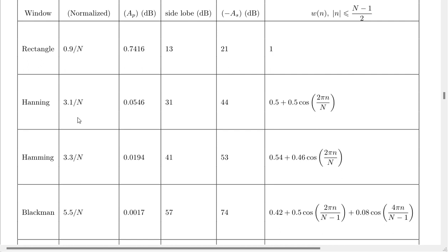Here N will be bigger than what you find for Hanning. And Blackman, of course, will have a lengthy window compared to these two. So, if the mentioned attenuation suffices, just stop and don't go more.